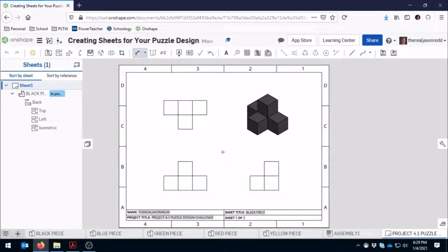But again, it really depends on the object and what it looks like, and that will determine which view you place the various dimensions in, the length, the height, and the depth dimensions. You will decide. So you need to follow the rules of dimensioning. How I dimension my objects might be slightly different than how you dimension your objects, but as long as we both follow the rules of dimensioning, we are good to go.